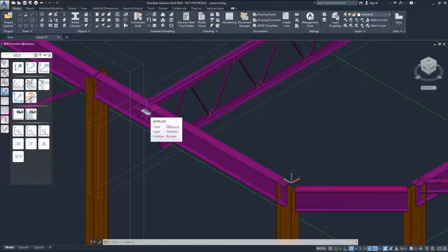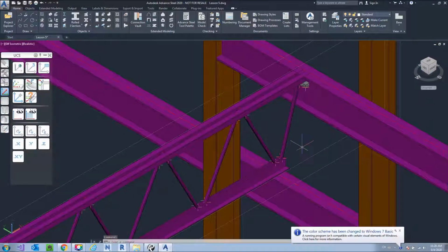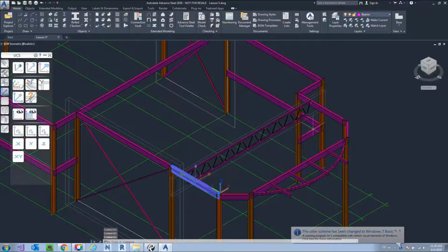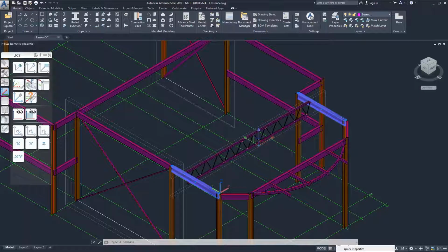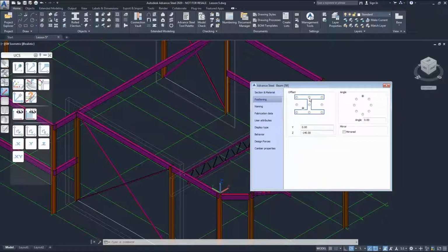The joints are not resting on the beam correctly on both ends. We correct this by moving the supporting beam to the correct height. We select the two beams and double click to get the advanced properties for the beams. This time we use the Positioning tab, Reference Position and the Offset to correct the height.